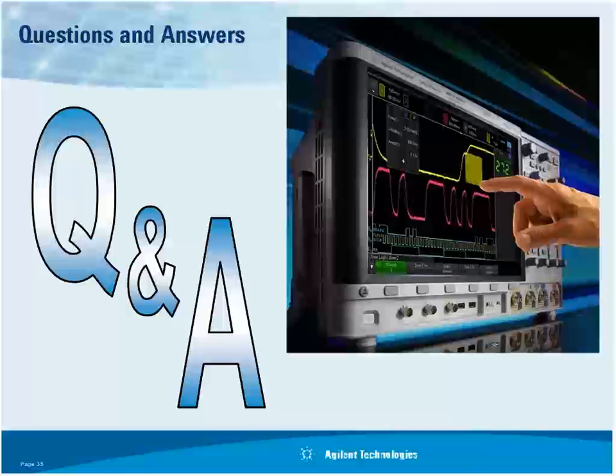Now, one easy way to make the current input measurement is typically you're going to have a power cord. Now, I probably shouldn't be recommending this because I'm probably going to get all sorts of safety issues thrown at me. You can strip back the insulation on the power cord and get a hold of that line wire within the insulation. If you get that insulation stripped back, you can easily clamp on to that particular one.